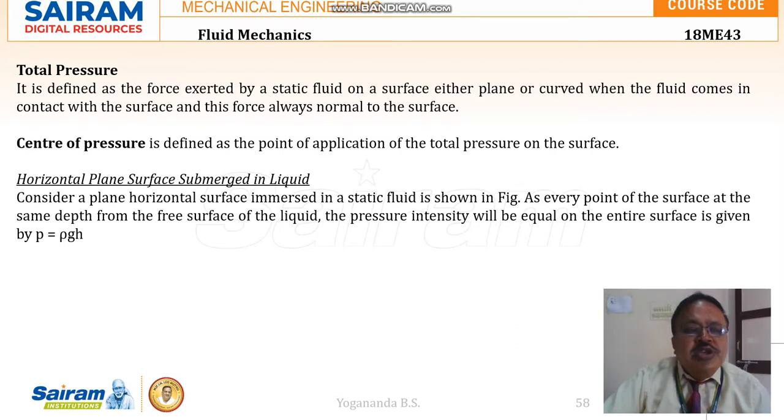This total pressure is always acting perpendicular to the surface. Center of pressure: the point where the total pressure is acting on this surface by the fluid which is in the state of rest is called the center of pressure.